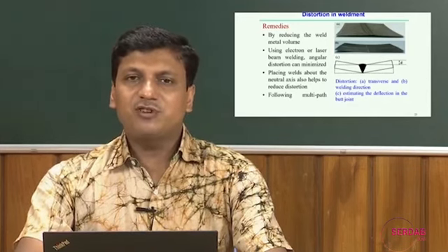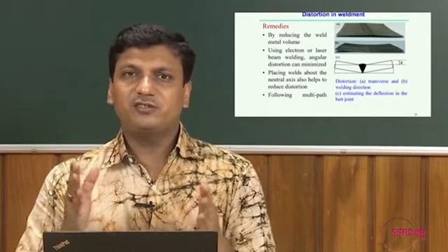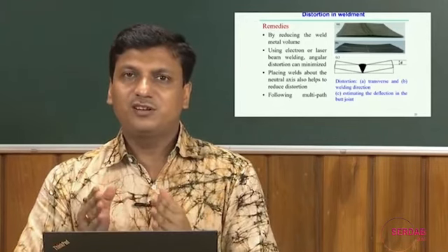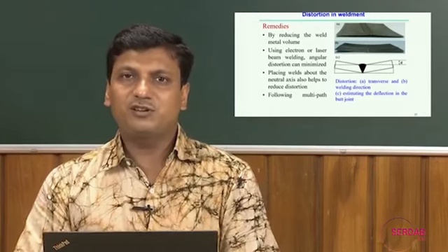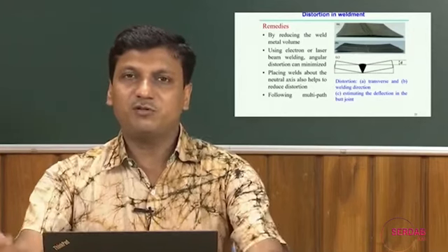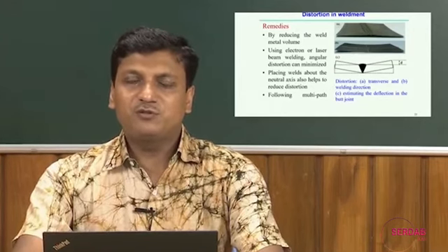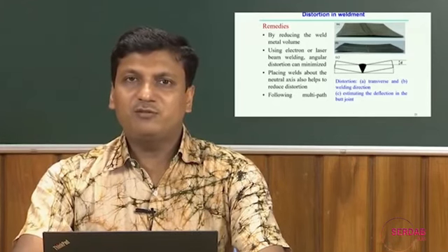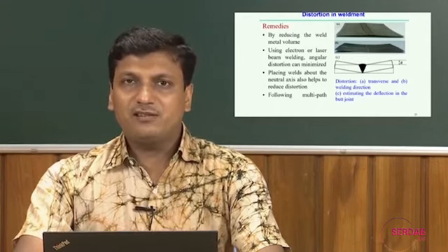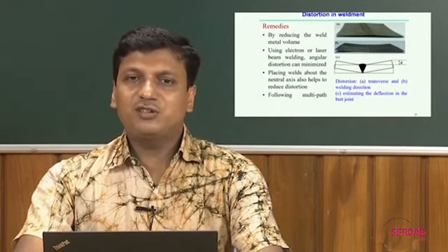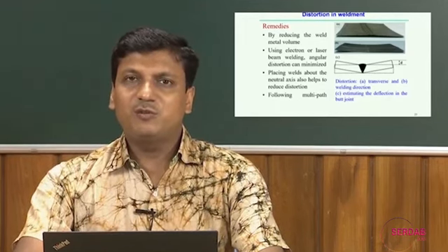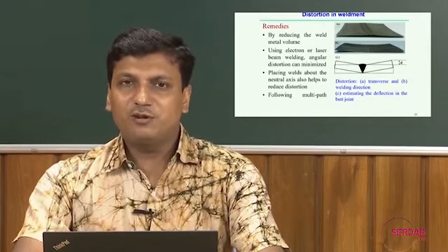Placing welds above the neutral axis, when you try to do a V joint kind of thing, there is a volume of the weld pool metal that is not uniform throughout the depth of penetration; it varies from maximum to minimum. So with respect to that type of cross section, if it is possible to place an equilibrated amount of the weld pool volume with respect to the neutral axis, then probably the amount of the distortion can be reduced.